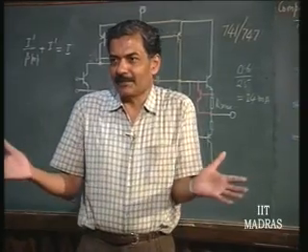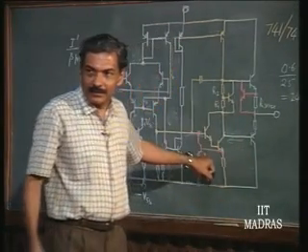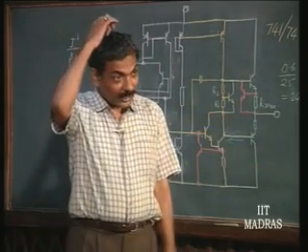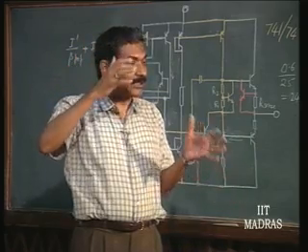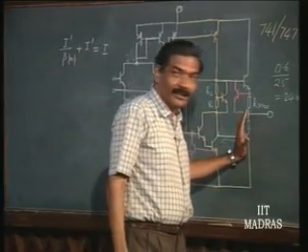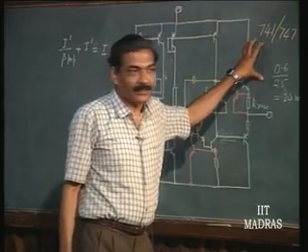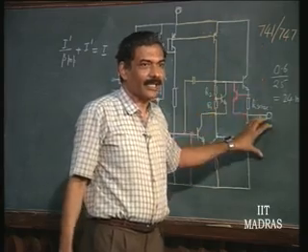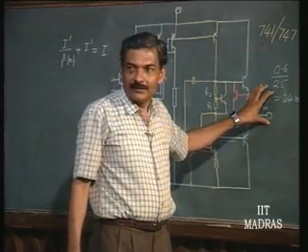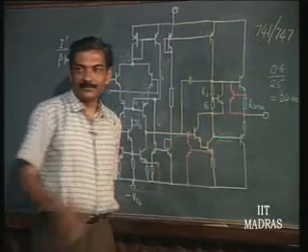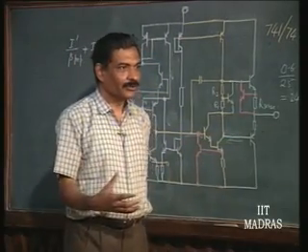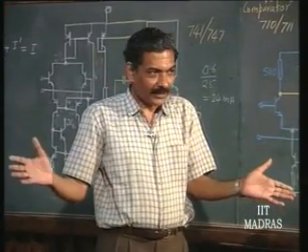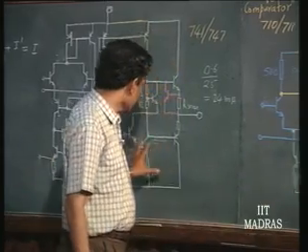Yeah, values are different. We are not very sure, because now this is beta dependent, right. Okay. So, this value is different from this. Okay. So, as long as it is offering some short circuit protection, it is protecting the output transistor, right. The rating for this transistor is totally different from this transistor, right. The current capability of this transistor and these are different. Okay. So, that is why these values are all different. Okay. That is what the designer has put, after a lot of tests and finding out possible variations of beta over the widest range of temperatures, etc., has put the suitable values here.